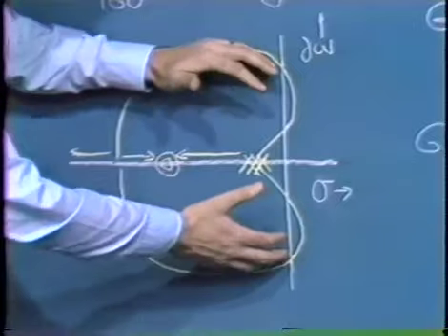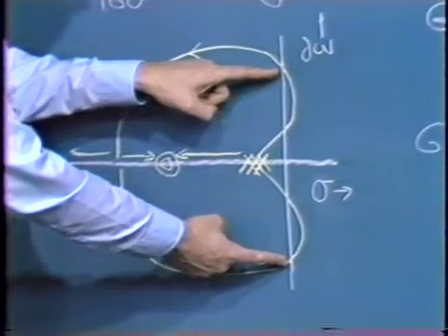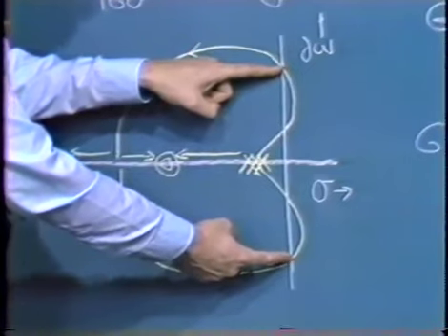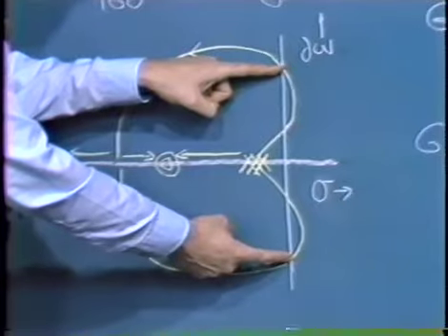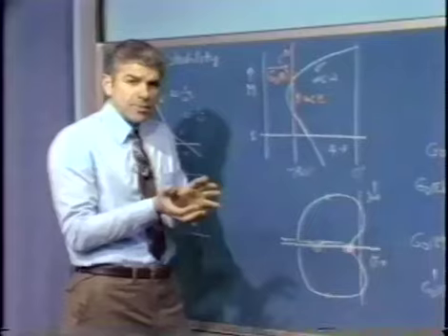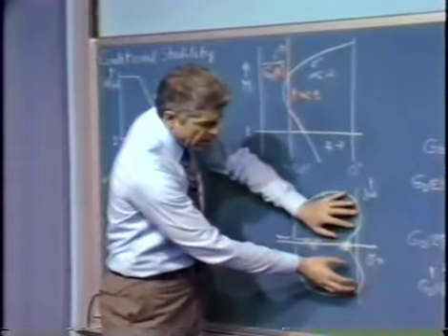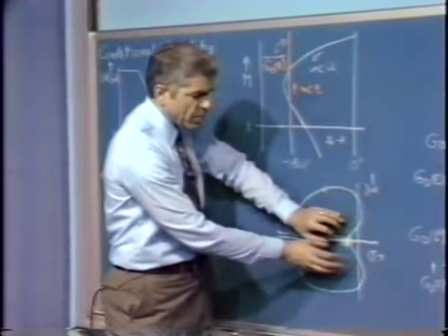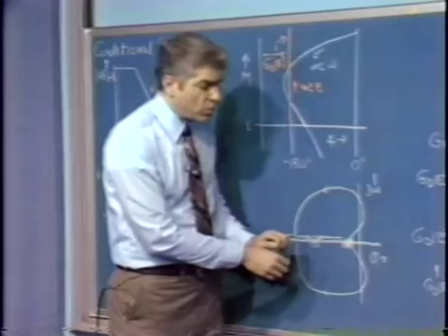The branches move back. For some sufficiently large amplitude at the input to the nonlinearity, we have a pair of complex conjugate poles on the imaginary axis. There's a potential for oscillation. If the amplitude at the input to the nonlinearity were further increased, again, we'd get a lower A0 F0 product, since the gain of the nonlinear element in the describing function sense would drop.